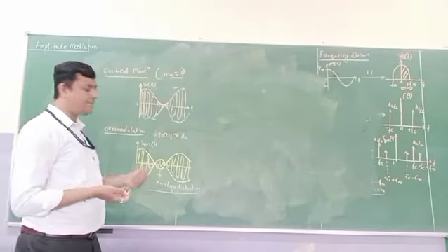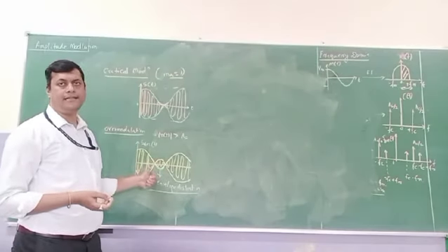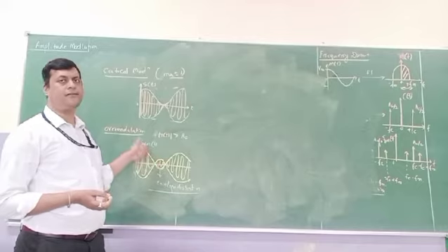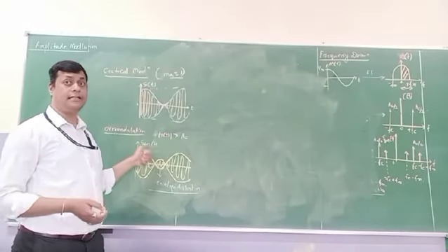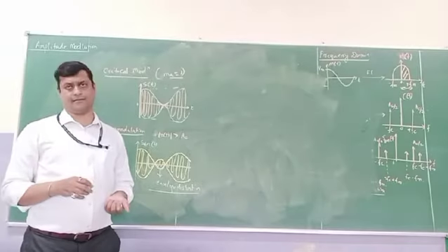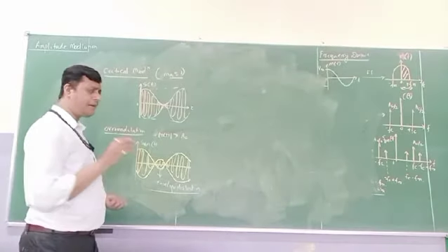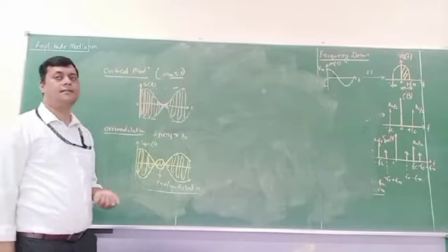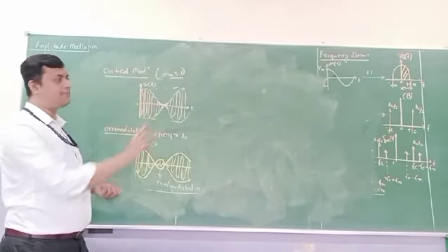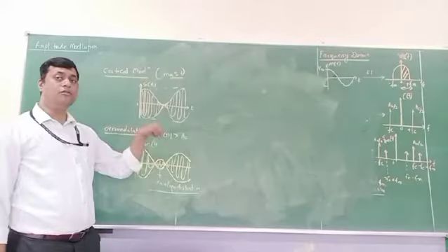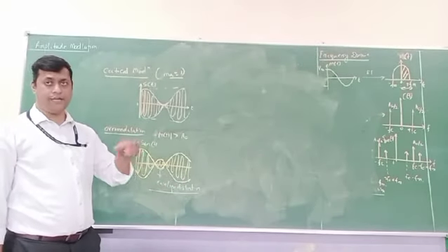So for practical cases, we avoid this particular modulation scheme, because in this case your modulating signal amplitude is greater than the amplitude of your carrier signal. For practical cases, critical modulation and under-modulation, what we have seen in our frequency spectrum, are what we are going to use. Over-modulation will contribute noise to your information.